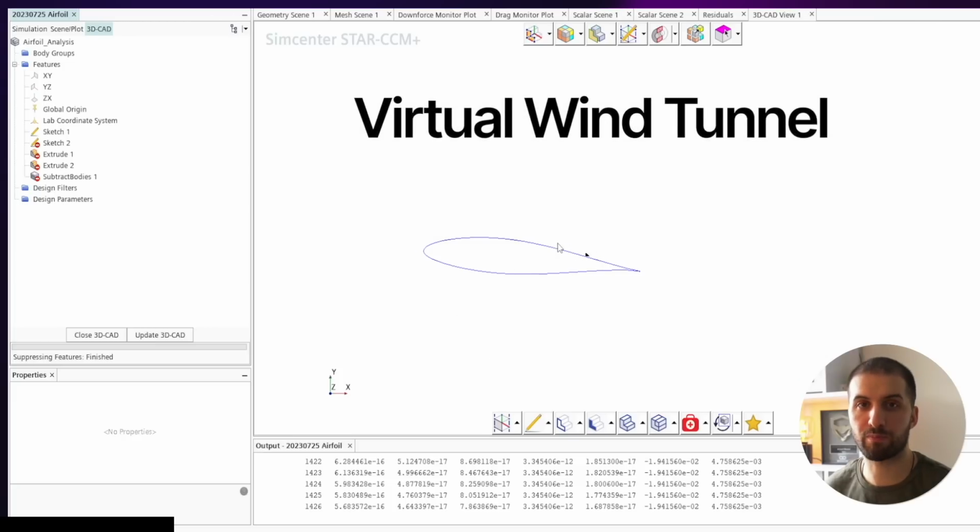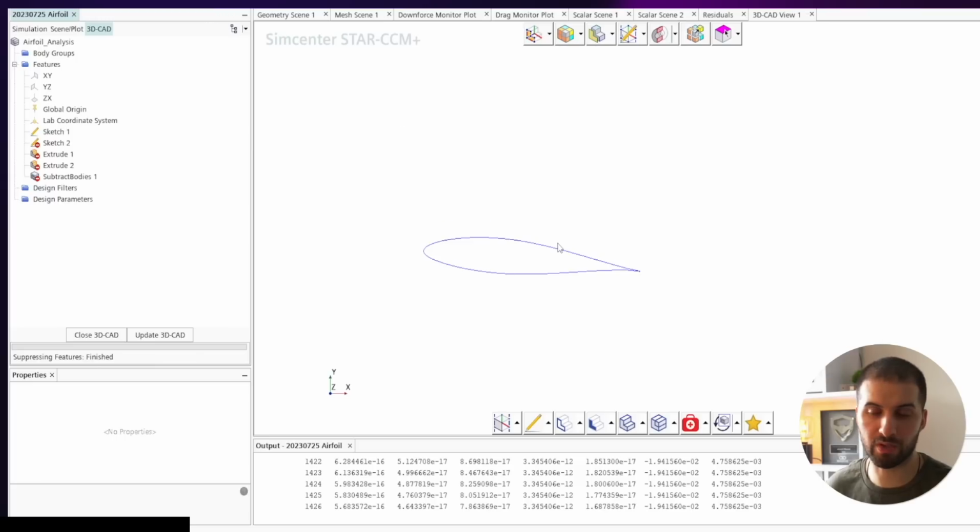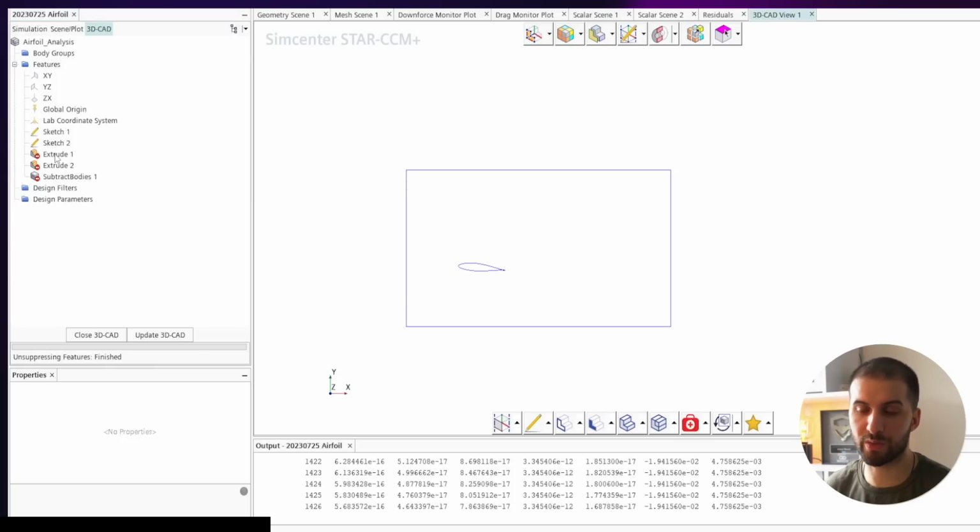And there's a few best practices. So for example, how big does the box have to be so that the boundaries of the box does not influence the fluid flow behavior around that airfoil. But there's even a few publications, papers around it. I think even not a few, but I think a couple of hundreds or thousands of publications talking about this.